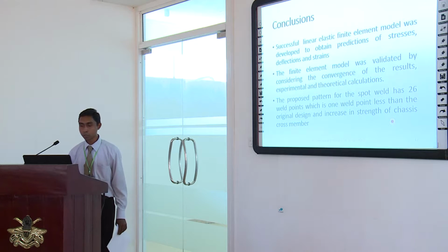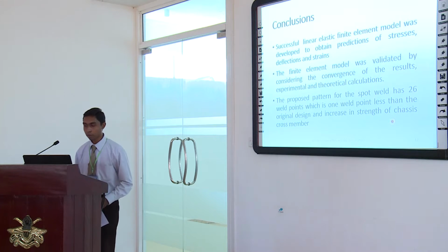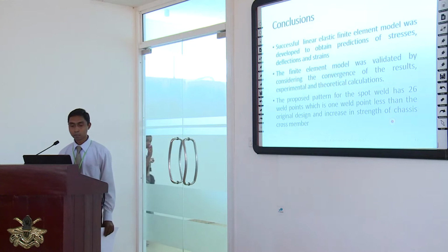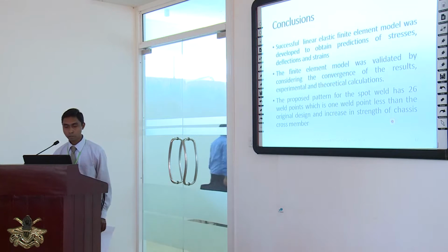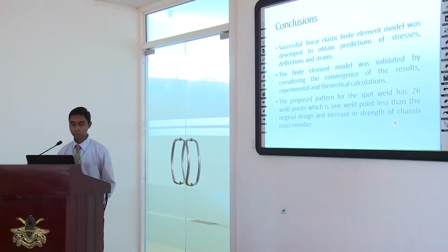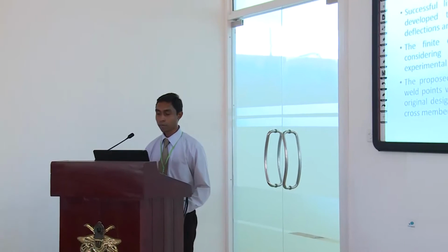So, as a conclusion, I could say that this successful linear elastic finite element model was developed to obtain predictions of stresses, deflection and strain, and it was validated by considering the convergence of experimental and theoretical results, and the proposed pattern where we could reduce the number of weld points, and the strength also increases.